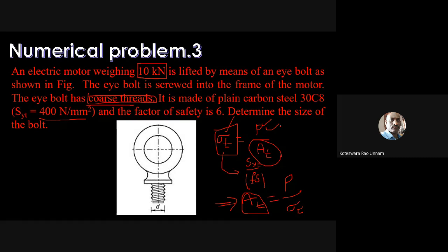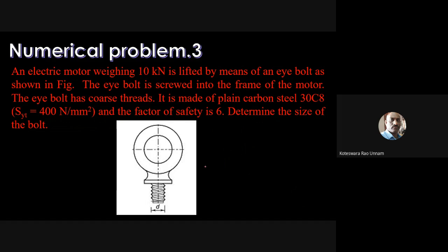Here is one more important point, where I think most of you will make a mistake: the conversion of units. Load is in kilonewtons, and stress is in Newton per mm square, so it is in newtons. You need to convert the load also into newtons. That is an important thing you need to remember. So that's it. That is the solution.